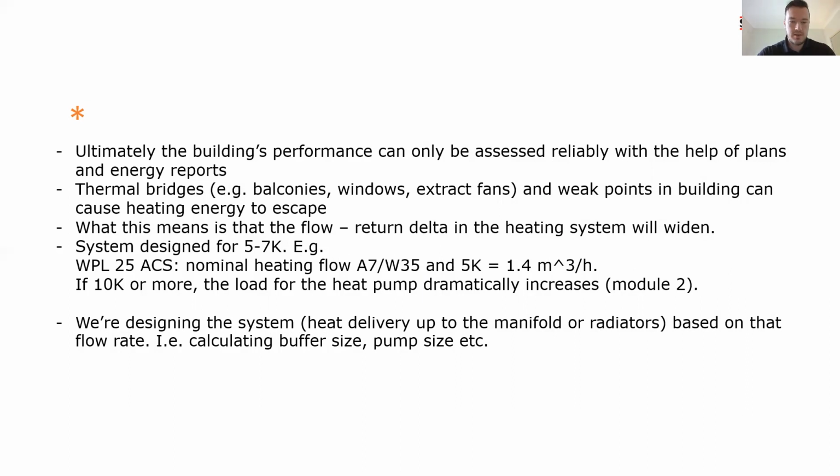So final sentence maybe, and we won't cover all of that. That's probably more one for a later session today, which is components, heat pump components. We're designing the system up to the manifold. And based on that, the flow rate, etc., determines the buffer size, the pump size, and so on and so forth. We'll look at a couple more buffer sizing examples in module 2, but just know that we design a holistic system, and every component that we throw into the mix will be designed around the flow rates of our heat pumps, essentially, and accommodate for those flow rates.